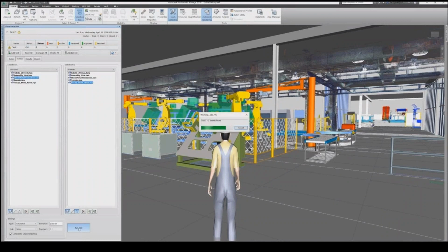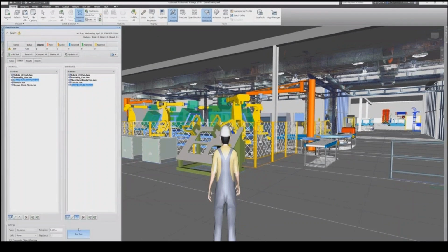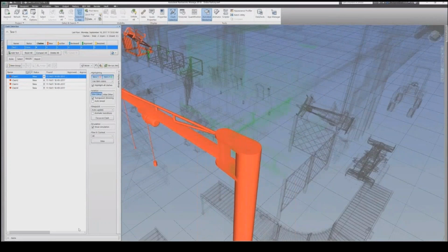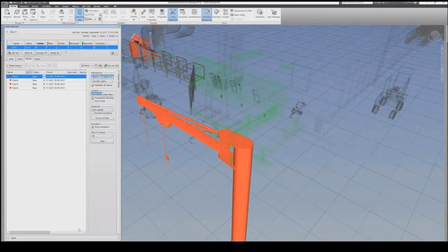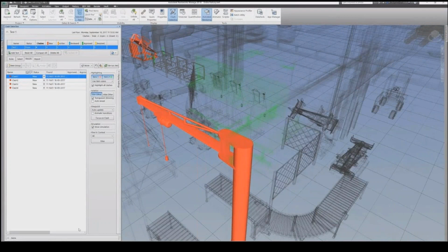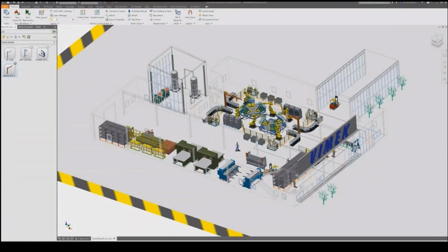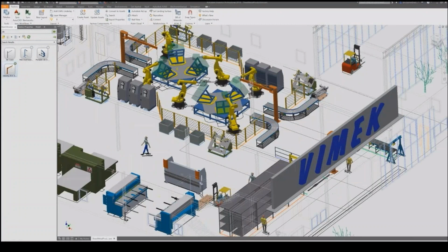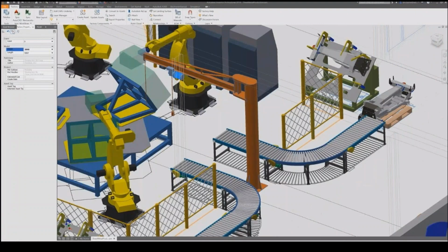Some factories will have modifications inside of them, but we can actually use a point cloud and do a clash detection to see if our new layout is having interferences with what's in the building. So instead of trying to remodel everything and measuring it, it's very complicated. Get a scanner, get a point cloud, put it inside Navisworks, and do your study there.